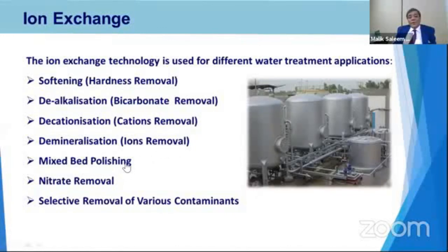For that, we require a mixed bed polisher or EDI. And in some water, nitrates are present, so we can have a selective ion removal resin as well.